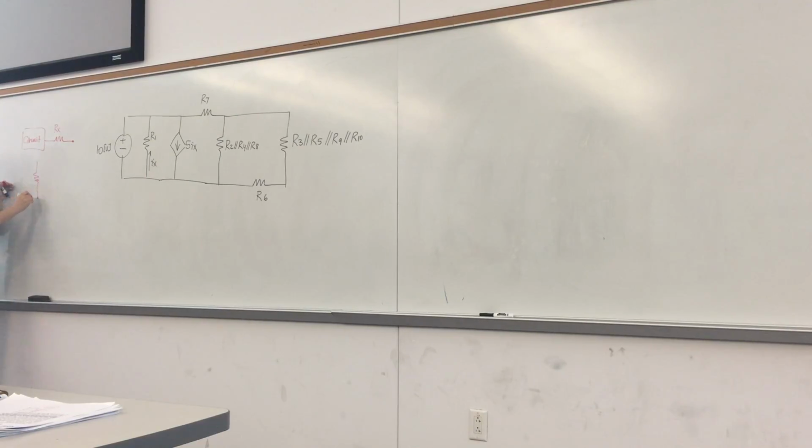If you have a resistor that is in parallel with a wire, that resistor is shorted, and it means that the voltage across this resistor is 0, which means current through it is also 0, right? For a resistor, I times R is V, right?